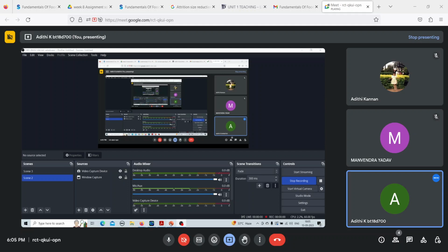For the next, you have sieve stage as 3, and the fraction of weight retained as 18 by 110, which is equal to 0.4909. Then again sieve stage 2 into fraction of weight retained 36 by 110, which gives you 0.6545. Then sieve stage 1 into 34 by 110, which gives you 0.3091.